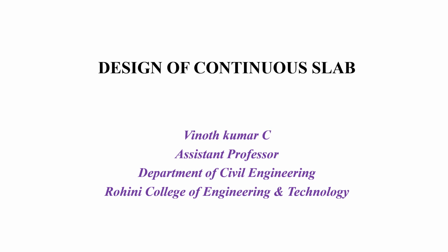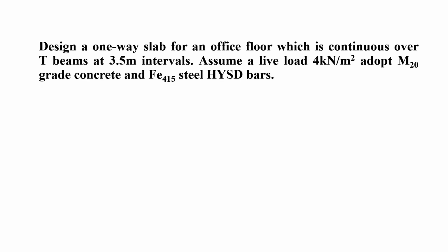Today we are going to learn a topic, continuous slab. In this continuous slab, we will see a problem. Design a one-way slab for an office floor which is continuous over T-beams at a 3.5 meter interval. Assume a live load of 4 kN per meter square. Adopt M20 grade concrete and Fe 415 steel HYSD bars.